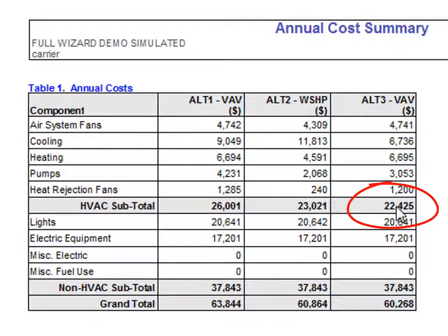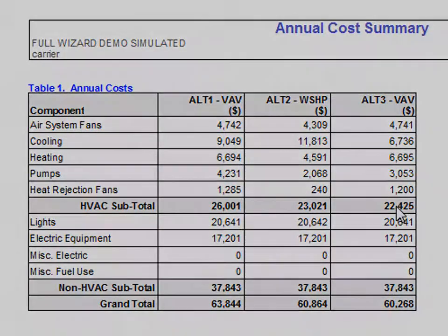Several features contribute to that result. It uses an air-side economizer and a higher efficiency water-cooled screw chiller with excellent part load characteristics. Also, the fans are equipped with VFDs for air-side savings at part load conditions. Since the full wizard project configuration is now imported into the HAP program, you can choose to modify the data within HAP and rerun results if you wish, or you may want to make the changes by running a standalone wizard. We will cover standalone wizard operation in a separate training session.